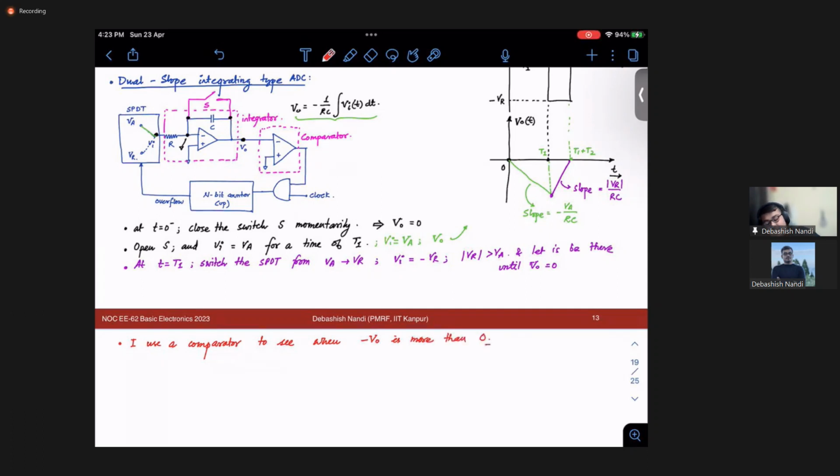Okay. That is what has been achieved by this comparator. So for 0 less than t less than T1 plus T2, let's say this input is your Vx, I will have Vx equal to 1. Okay. So one input of my AND gate will be 1 always during that time. Fine.